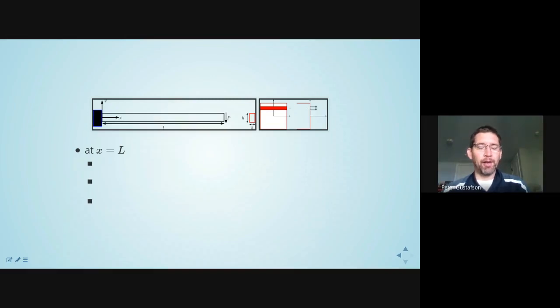Okay, so the next boundary that I'm interested in is the right-hand side. In our geometric description, this should be at z equals L. I apologize, I've written it as x. It should be z. So at z equals L, what is our boundary condition? It's not quite as simple as being zero traction this time, right? Because now, in fact, we have this overall force resultant, which I've described as having a magnitude of P, point force P. Traction is P in the negative y direction.